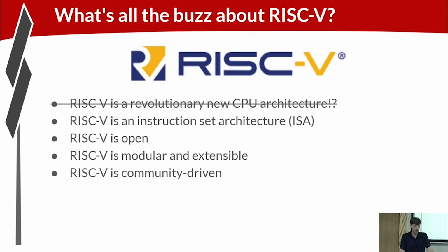What's maybe the most real aspect of RISC-V is that it's modular and extensible. So it's defined with these extensions. You've got the base instruction set that's only, I don't know, 40 some odd instructions, very simple. We're going to implement almost all of them. So you can have very simple RISC-V cores that will execute programs. And then you have extensions that build on top of that.